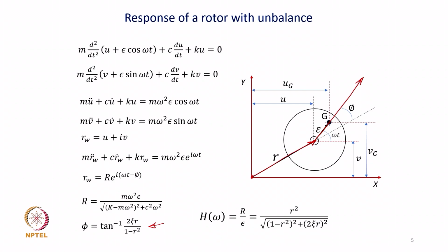Okay. So, the shaft center position is where we get the response, and obviously the response lags the force by an angle phi. So, the force will go first, will reach its peak value first, and the response will follow. Okay. That is what we have here as details of a rotor vibration case. Phi is the phase with which the response lags the excitation force.